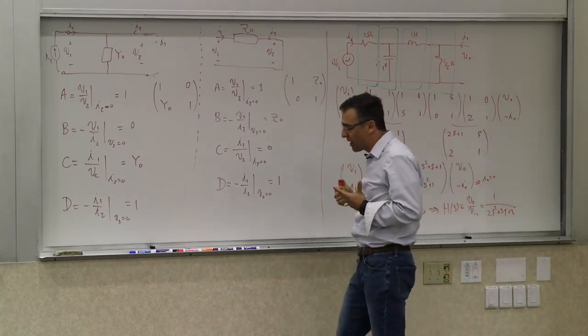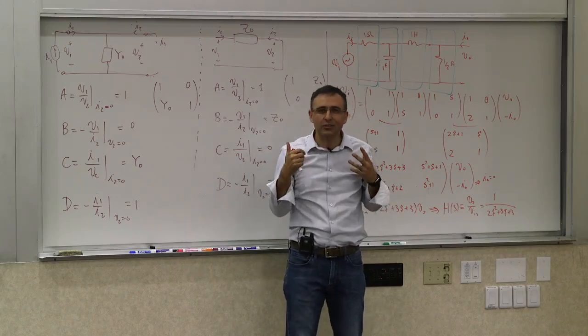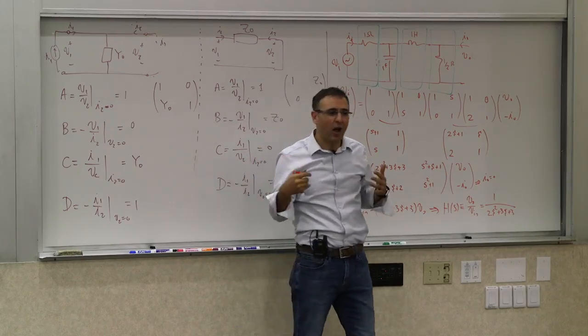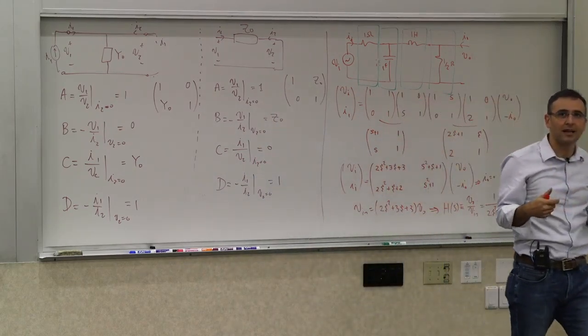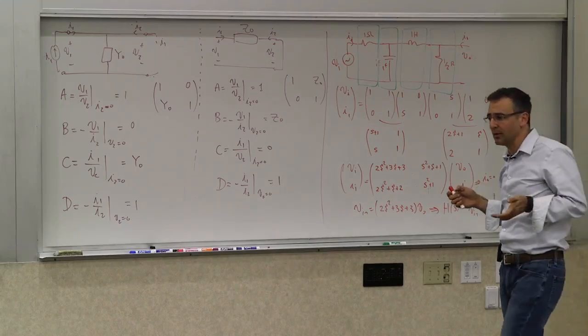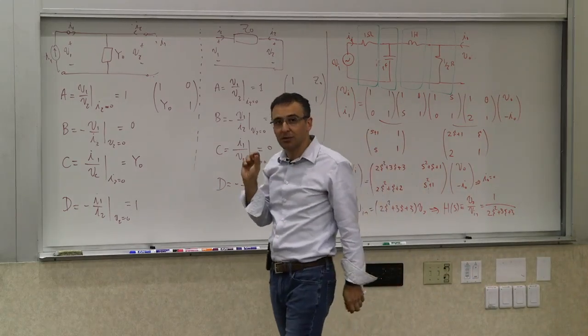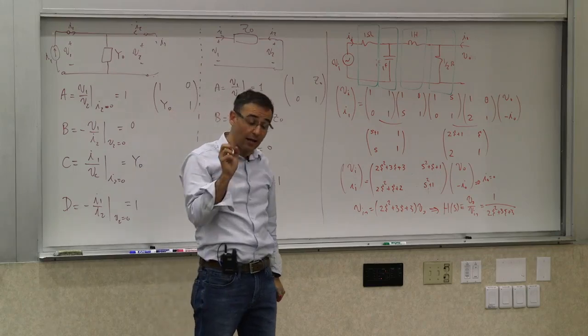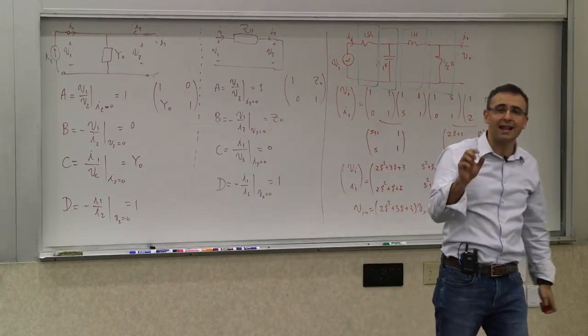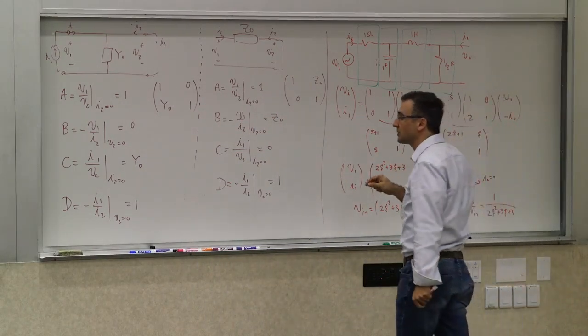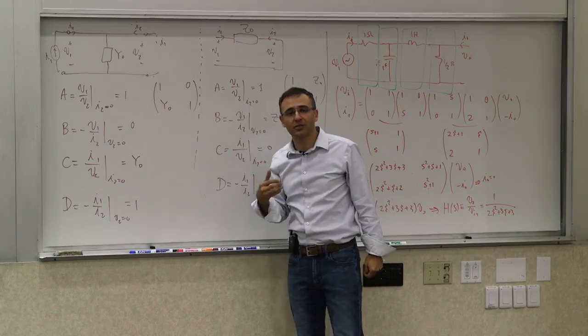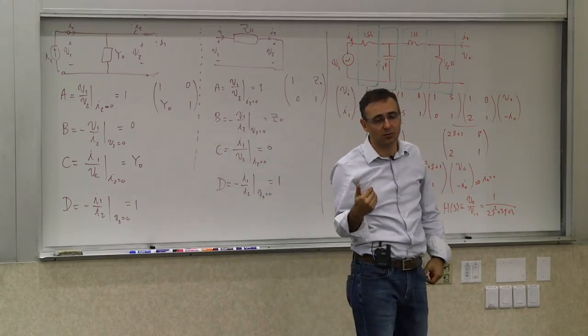The reason is that making a precise short or open at very high frequencies is very difficult, because any short will have some inductance, and any open will have some capacitance. So as you go to higher frequency, it will have a sufficiently large impedance to cause a problem.